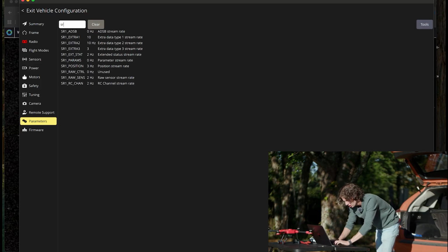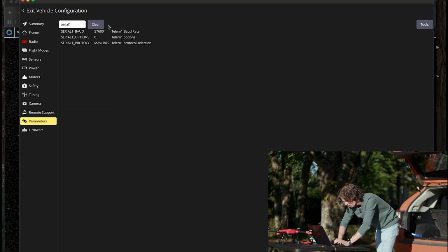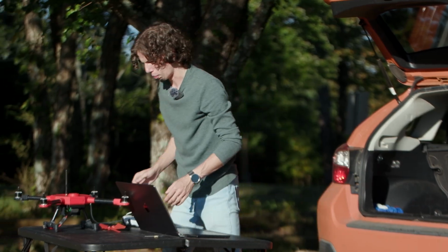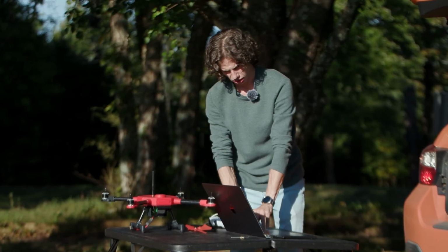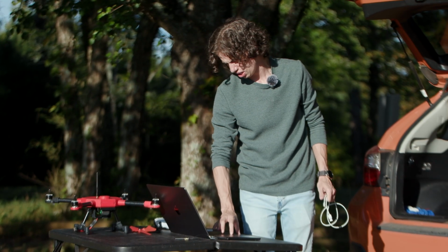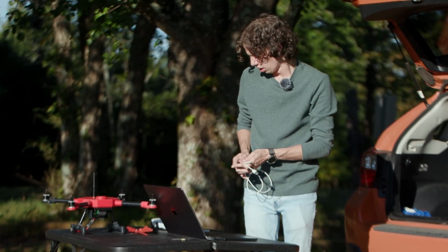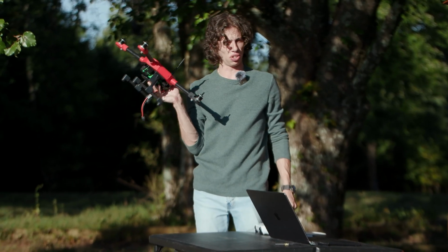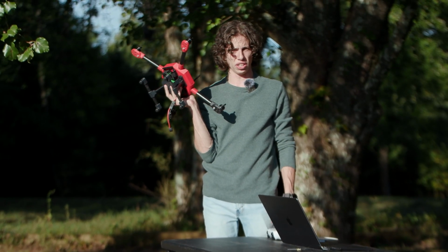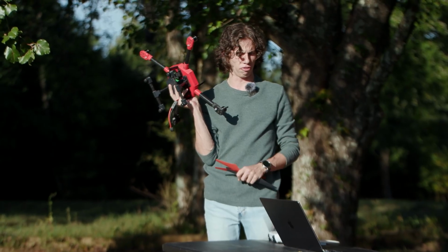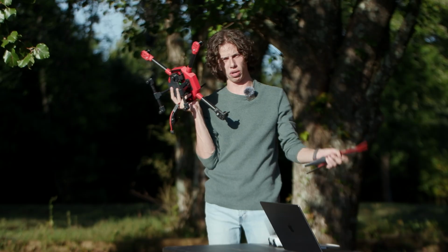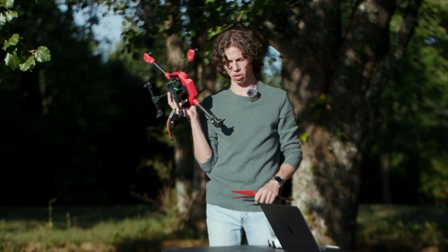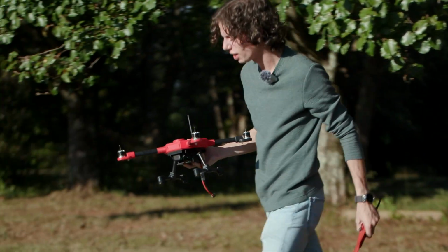All right, and then serial 1. All right. I think we should be good from a parameters perspective, so just going to unplug Develop Air from USB communication. We're going to go set Develop Air out in the field. We're going to open up QGroundControl just to see if we're getting any error warnings or messages, but we'll first attempt flight in the iVue RC app. If that does not work, we'll switch back to QGroundControl, see if we're achieving flight there, and then we'll see what happens next.